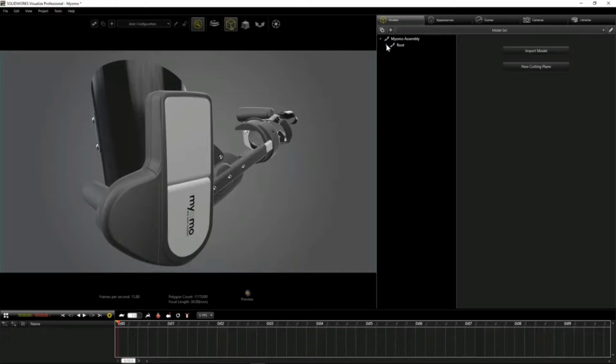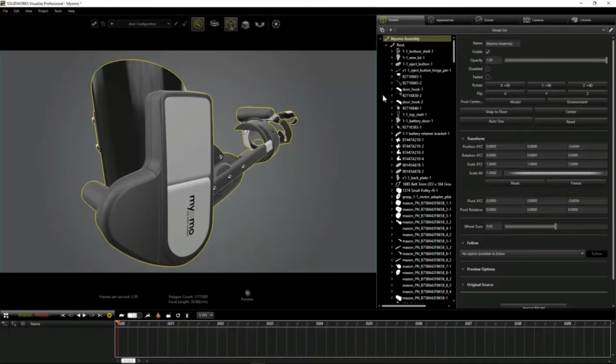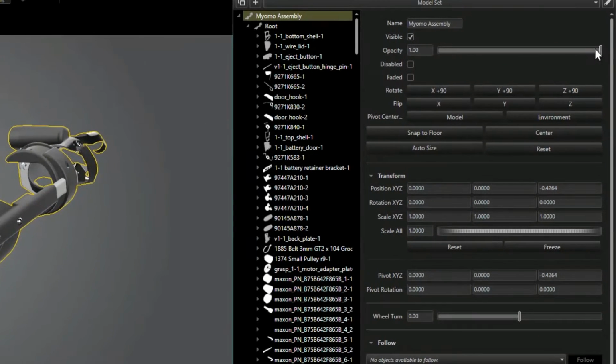One of the new items that SOLIDWORKS Visualize 2017 allows us to do is to change the transparency either of the entire model, or you can just pick and choose individual faces. Here's just an example of how you can use this slider bar to show some of the items that are necessary perhaps to show inside our part, so we can hide some walls, etc.